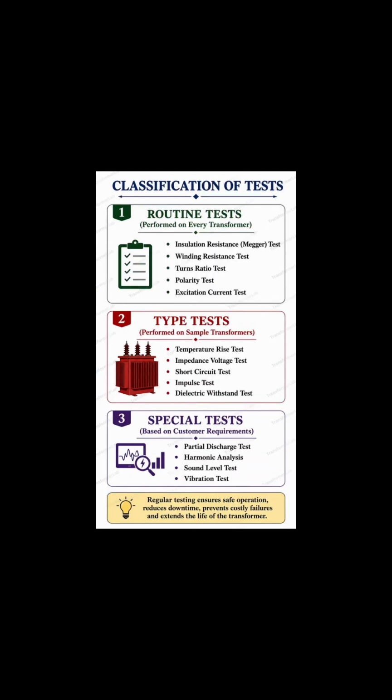Classification of transformer tests. 1. Routine tests performed on every transformer: insulation resistance test, winding resistance test, turns ratio test, polarity test, excitation current test. 2. Type tests performed on sample transformers: temperature rise test, impulse test, short circuit test. 3. Special tests based on customer requirement: partial discharge test, harmonic analysis, sound level test.